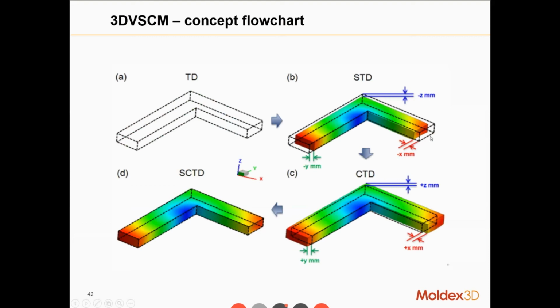After we simulate this part, we have a simulated target design, which will have a warpage phenomenon, and the part will shrink along the x, y, and z axis with distance.